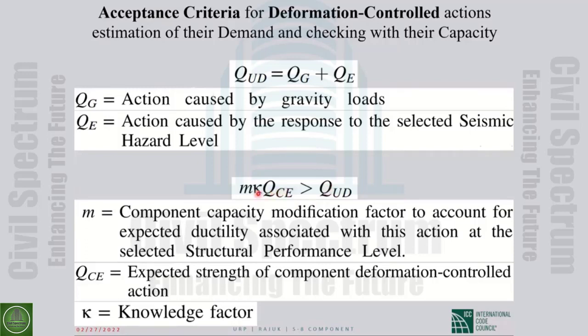But we look at the values of M that give us a sense of how much damage is accepted for this element. This M value naturally should depend on the properties of the element, also on the performance level that is selected. And then there is a knowledge factor I will explain later.